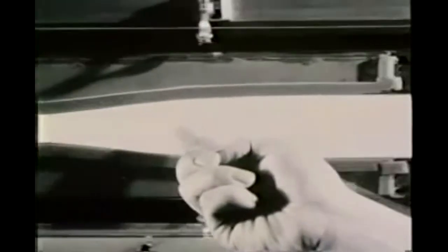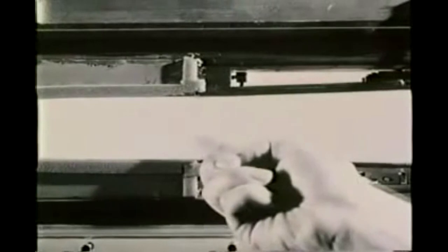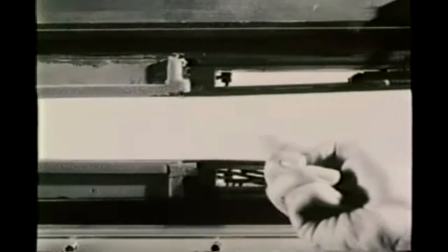We've now changed our channel geometry. First, we have a short symmetrical nozzle designed to give uniform flow at a Mach number of about 2.3 in this test section. Then we have an adjustable second throat, which can be opened or closed to vary the amount of supersonic compression.